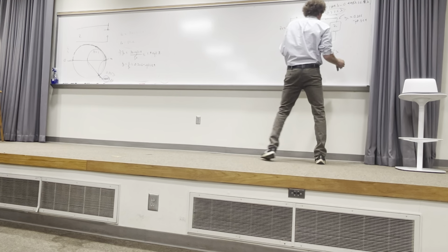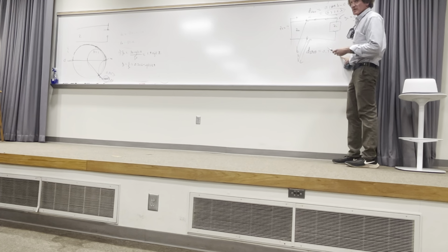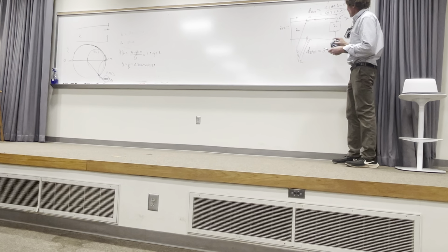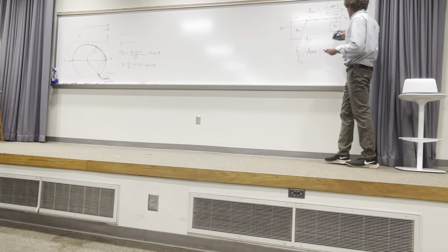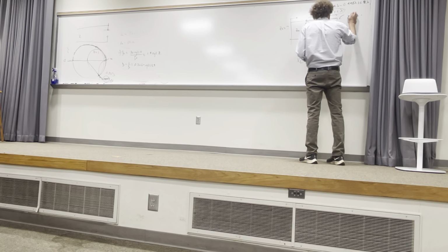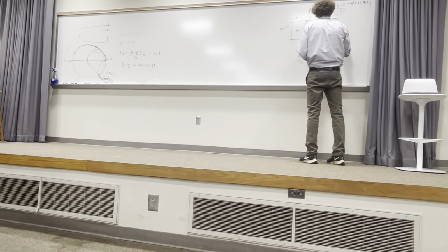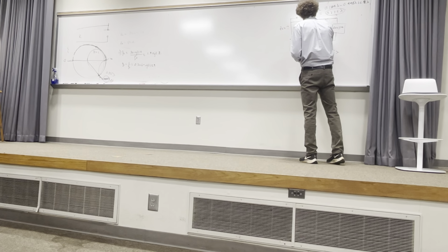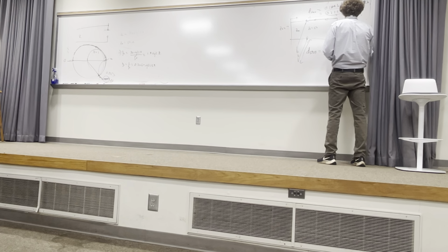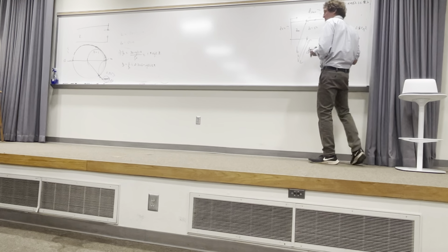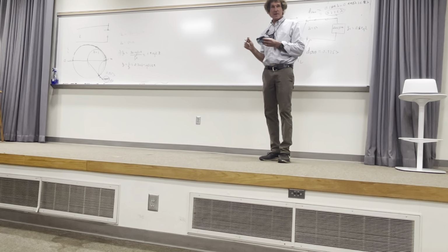All right. This is the length of the stub. We're saying that stays the same, the length of the stub stays the same, the connection point stays the same. We're changing this. And what was the new value? 40 plus j100 ohms. Z naught is still 50, right? Yes, sir. So that means my normalized load impedance is going to be 0.8 plus j2, correct? Yes.